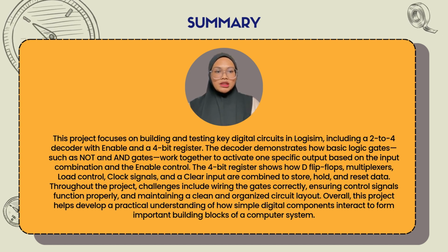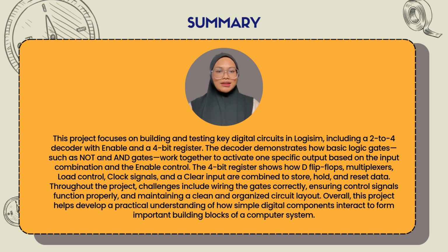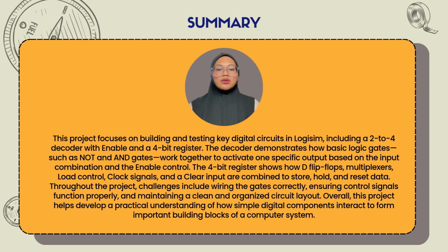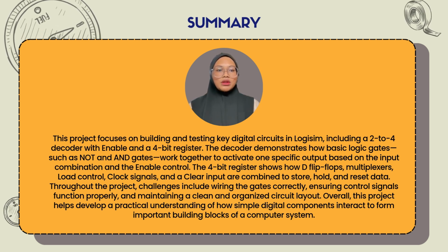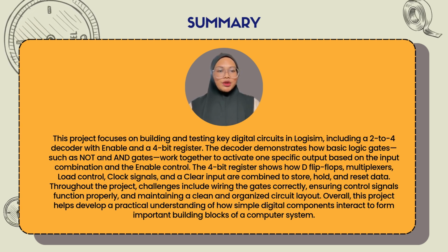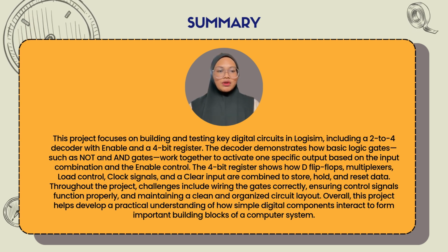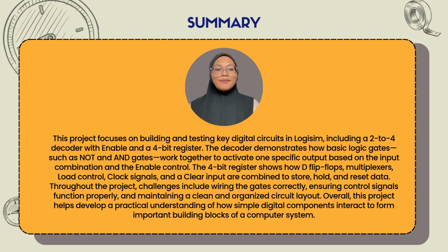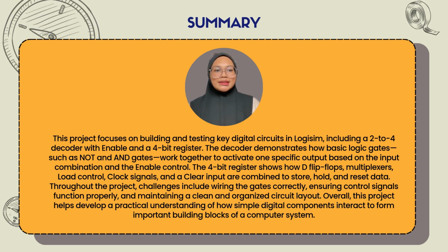The 4-bit register shows how D flip-flops, multiplexers, load controls, clock signals, and a clear input are combined to store, hold, and reset data. Throughout the project, challenges include wiring the gates correctly, ensuring control signals function properly, and maintaining a clean and organized circuit layout.